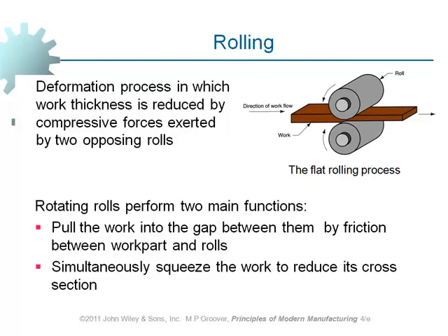Okay? I'm not saying it's unlimited because the magnitude of the deformation which is taking place should be proportional to the number and percentage of the dislocations which are present in the material. If the magnitude of the deformation is beyond that, even a material at elevated temperature or above recrystallization temperature may fail. However, we can subject the material to much more deformation at elevated temperature.